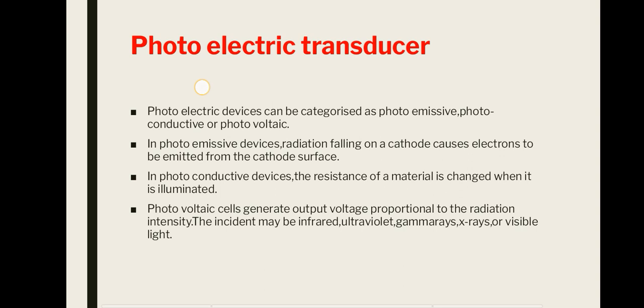The next topic is the photomultiplier tube. The photomultiplier tube consists of an evacuated glass envelope containing a photocathode, an anode and several additional electrodes termed dynodes, each at a higher voltage than the previous dynode. This figure illustrates the principle of the photomultiplier. Electrons are emitted by the cathode and attracted to the first dynode. Here a phenomenon known as secondary emission takes place.